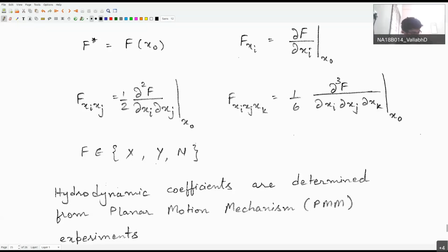So in both the first principles approach and the approach based on experiments, we will have one term, say X mod u. So that will have that CF part, right? So in the first principles approach, that CF, are we calculating it based on the scale model only? Correct. Either you can calculate it based on the scale model or any available data for similar ship types also you can directly use. So you need not always conduct the experiments.